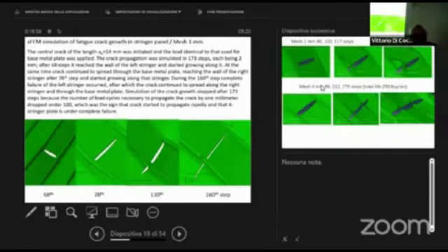Here you can see a couple of nice results showing different steps for the mesh with 1 millimeter size elements. After 68 steps, the crack reached the first, left stiffener. Then after 78, you can see that it goes up and through the stiffener. And then after 138, it goes both ways, already in the next segment of the panel.